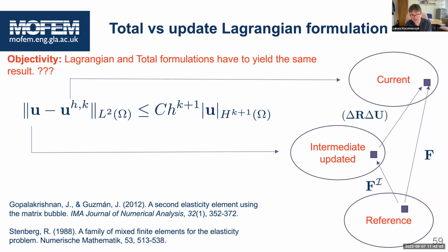It's improving your solution because you can see the norm, the K plus 1 is jumping up. So then error drops by projection itself. And then on top of that, it gives you estimation of the error, which can drive your mesh adaptivity when your structure undergoes large deformations.